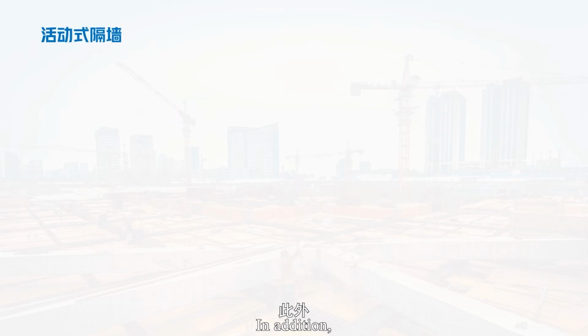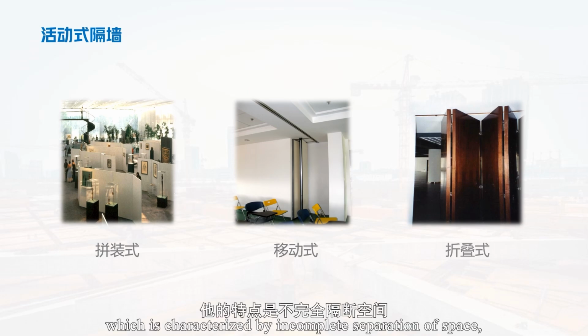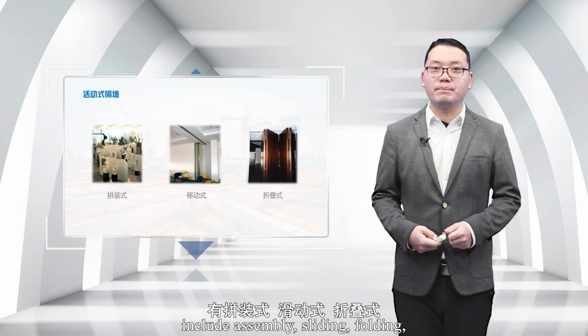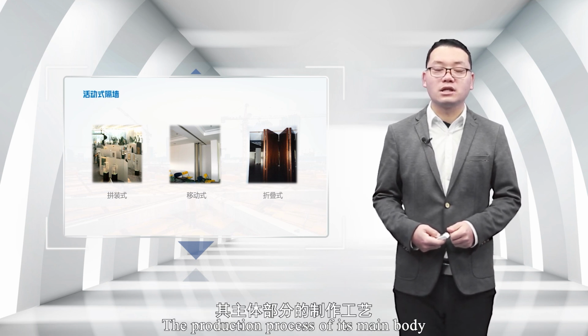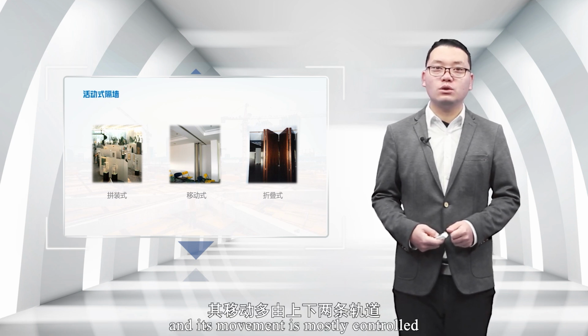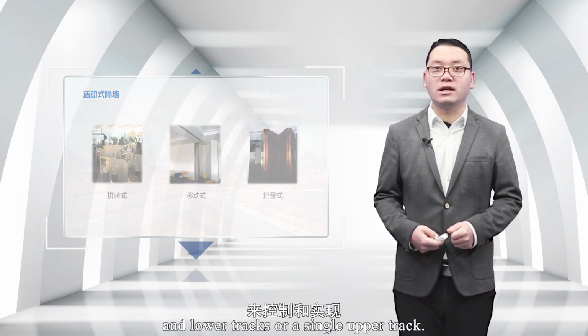In addition, there is a type of movable partition wall, which is characterized by incomplete separation of space, mainly serving as a partial obstruction or organizing traffic routes. The common forms of movable partition walls include assembly, sliding, folding, suspension, rolling shutter, and lifting. The production process of its main body can refer to the method of door leaf, and its movement is mostly controlled and implemented by two upper and lower tracks or a single upper track.